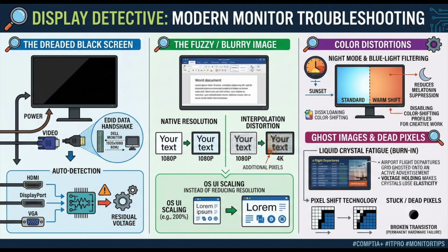That is a classic handoff failure. It's a failure between two completely different software environments. When you first hit the power button, your operating system, like Windows, isn't running yet. What you are seeing initially is the computer's motherboard executing its basic input-output system, the BIOS. Okay. And the BIOS is designed for maximum compatibility. It outputs a very low-resolution, incredibly basic display signal that every single monitor logic board on Earth is programmed to understand. So the BIOS is essentially using baby talk to guarantee the monitor can hear it. That's a perfect way to describe it, yes.